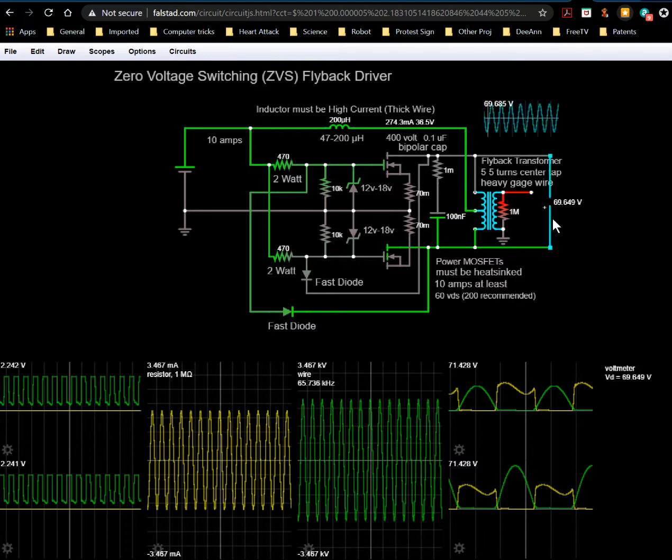Alright, which you can see, that's kind of the case, because here's my positive sign. So I'm measuring this positive here and negative here. That's why this is a positive voltage, because of how I'm measuring it. If you realize that this is connected to ground, that means the voltage across this capacitor is with respect to ground. So that's like 69 volts above this voltage level here.